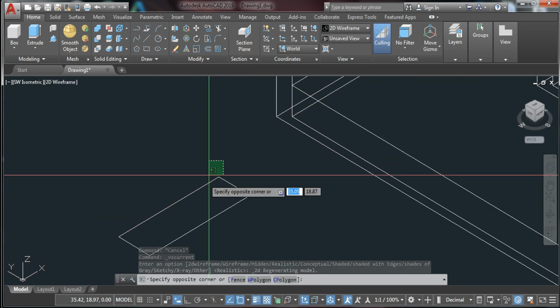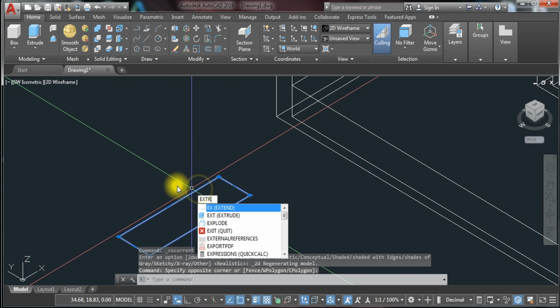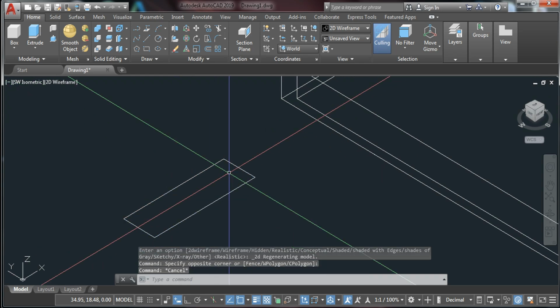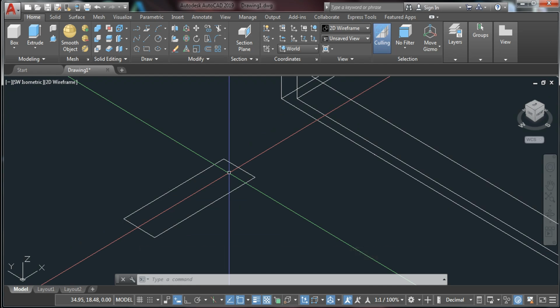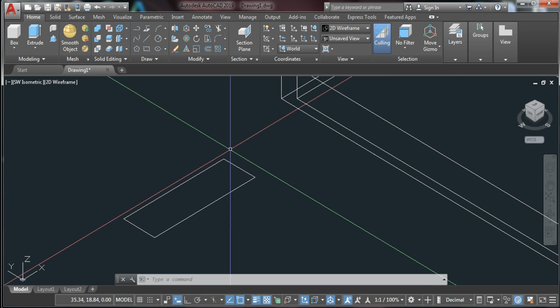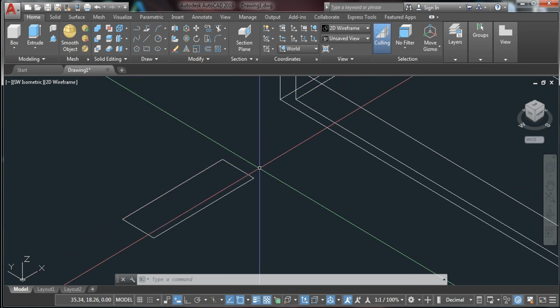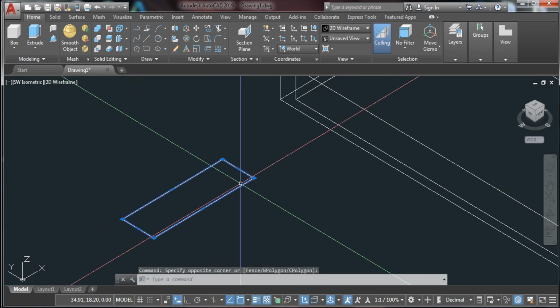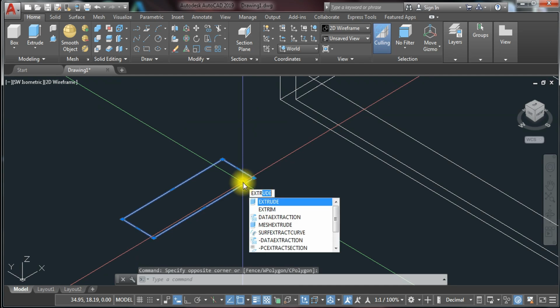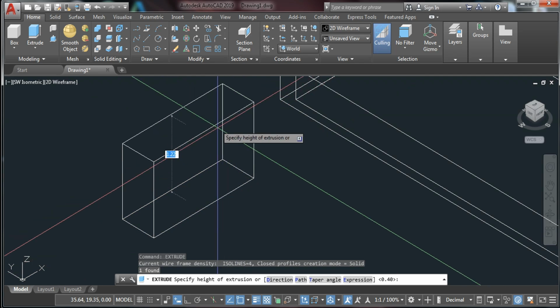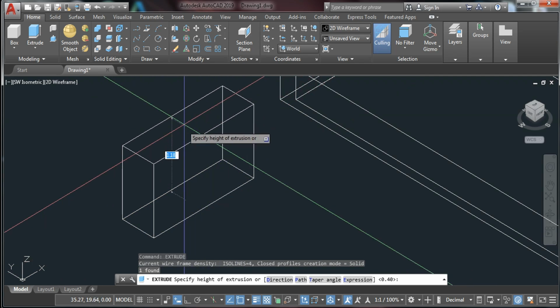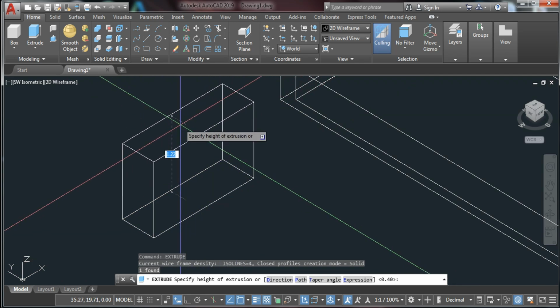Now, for laboratory, I'm going to have this extrude. Okay. So, there are two types of, should I say, actually marami talaga, no? But basic lang muna pag-aralan natin, we are going to have extrude and press pull, especially sa mga residential. Okay. Itong rectangular command, I'm going to right away type an extrude. Okay, as you can see, it also pulls up the object. Okay, it creates a 3D object.